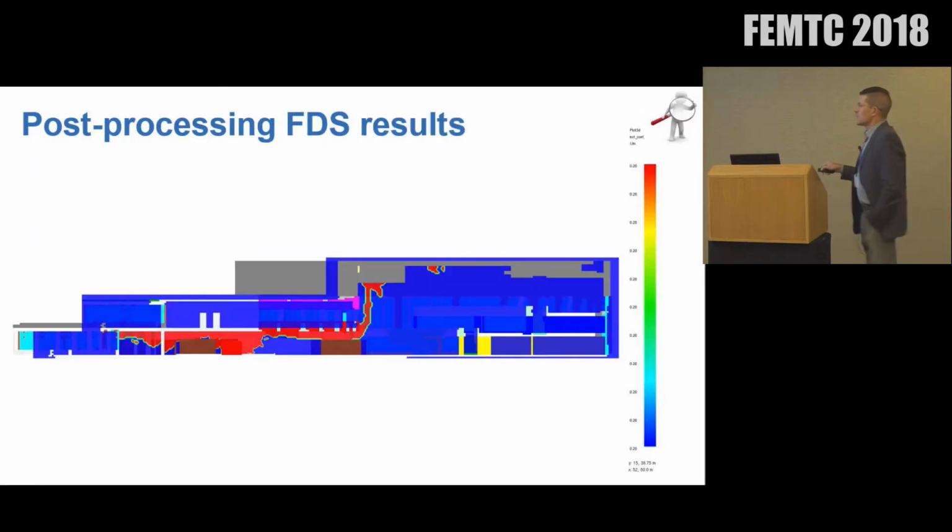That was the most complicated thing in this building: if you have a fire here, the smoke layer is difficult to keep in good condition. And one condition from the authority was to fix the extinction coefficient to 0.2. It's very severe, and you can see if you use this, people have their head in the smoke, so it's not good. But we thought that if you change this parameter, we can easily cope with 0.3 or 0.4 because the situation was good, with the aid of the evacuation simulation too.